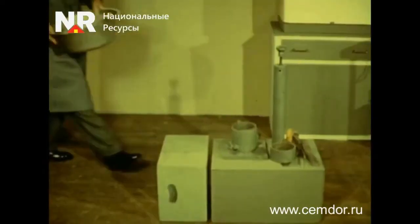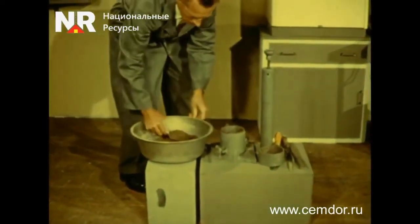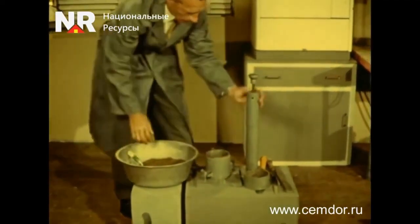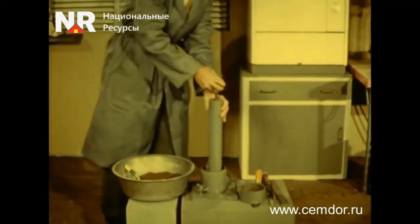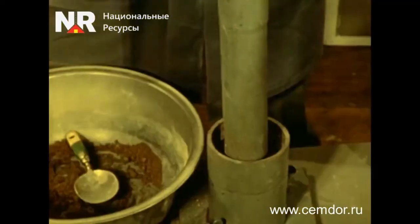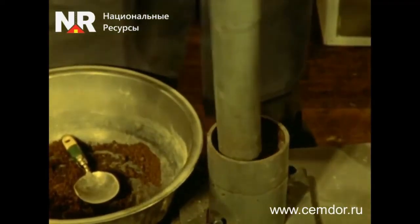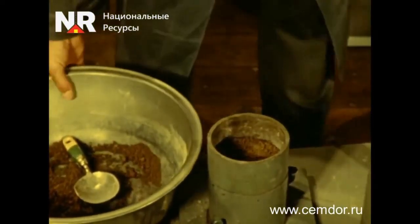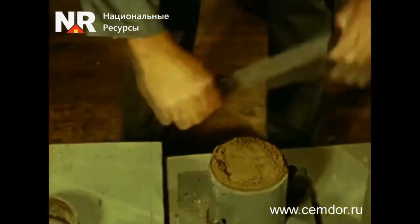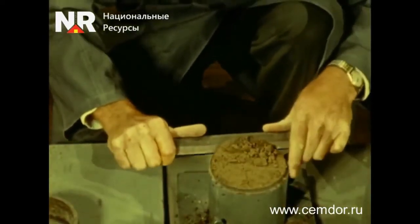To determine the maximum density and optimal moisture content of the soil, the test sample is loaded into a special mold in layers and compacted. After compaction, the collar is removed and the protruding part of the soil is trimmed flush with the edge of the mold.